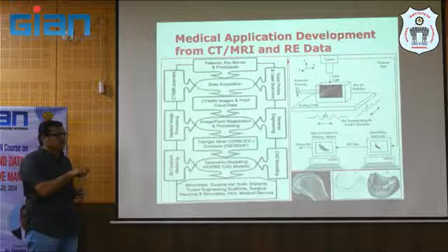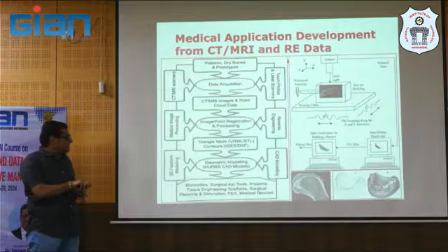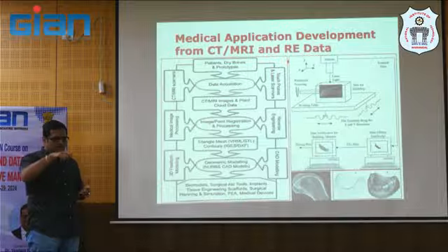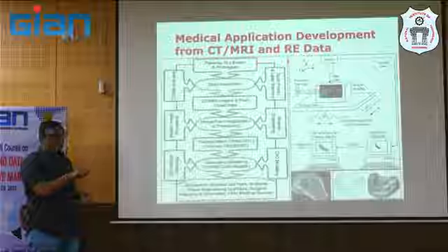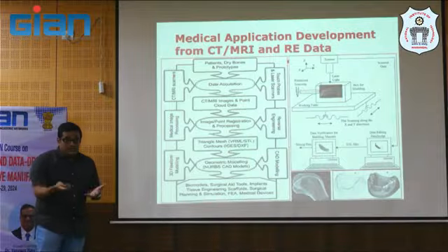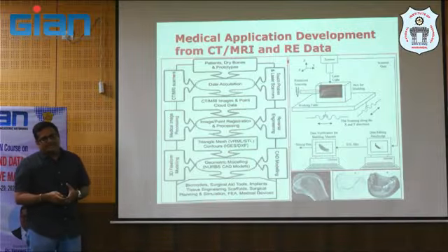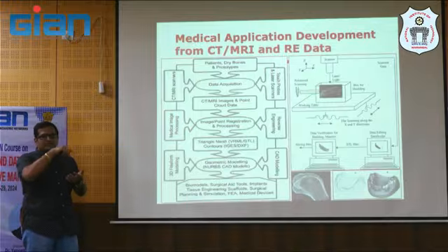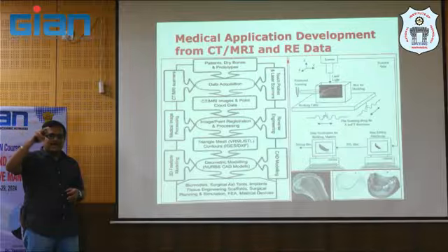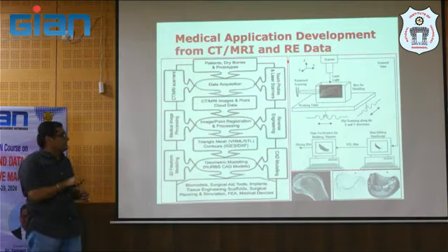Or even in the case of dental dentures, you are trying to get the outer surface. So in that case, go with any 3D scanner. Normally you use a 3D digitizer, 3D scanner, which can capture in terms of point clouds, and you fit those points like triangles, in this case STL, and you fit a surface or a solid. So your job is done, right?